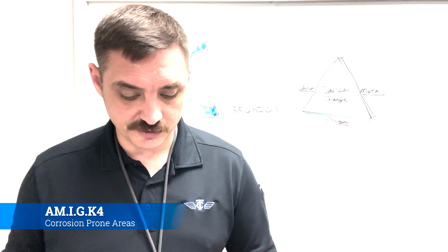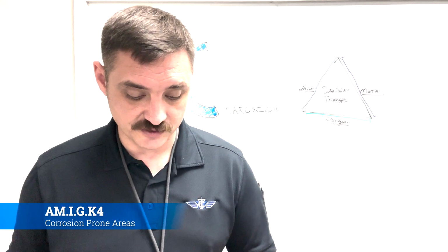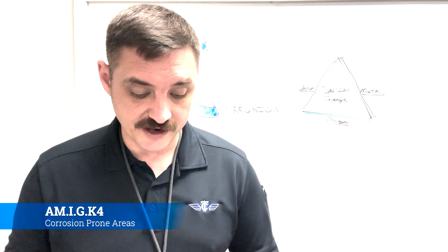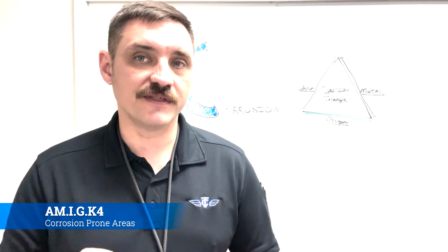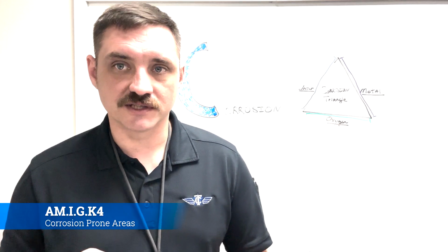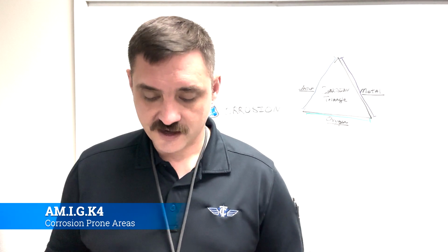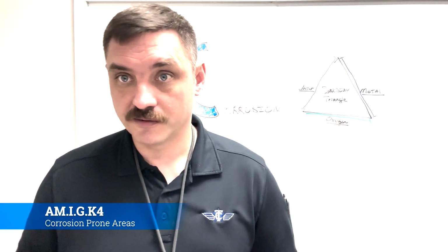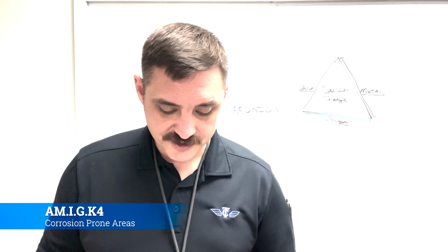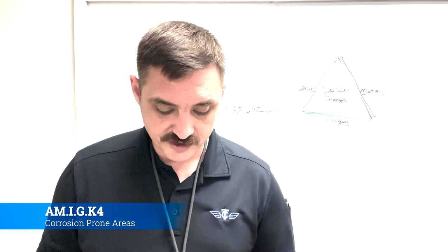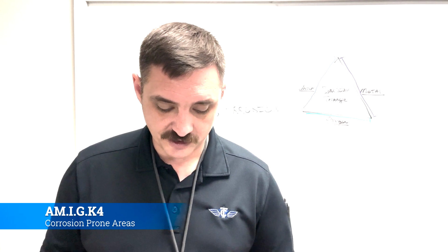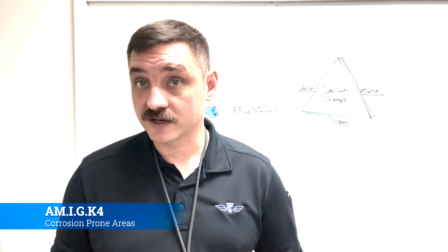There's a couple more that they really flesh out pretty well. Relatively little corrosion trouble is experienced with magnesium skins when original surface finish and insulation are adequately maintained. But the moment that you start to tamper with the surface, such as any sort of work on it, you'll end up having corrosion potential there. Piano type hinges are prime spots for corrosion due to the dissimilar metal contact between the steel pin and aluminum hinge. Also, it will trap dirt and things like that.